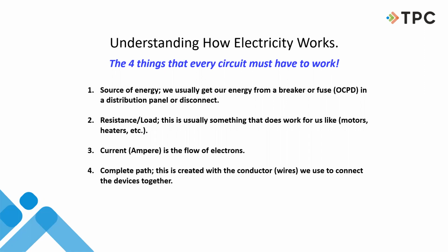So I should know that I'm working on 24 volt controls, or I'm working on 120 volt controls, and all that information is going to be on that drawing. So our source of energy is important to know. Also, we're going to get our overcurrent protection devices on our drawing. So fuses, breakers are important to know.